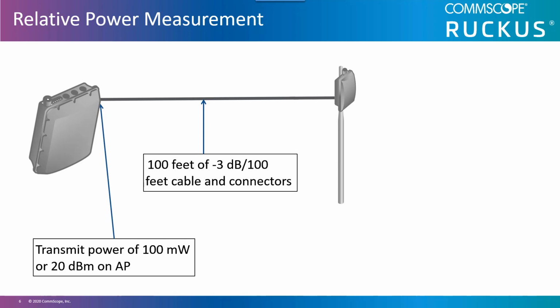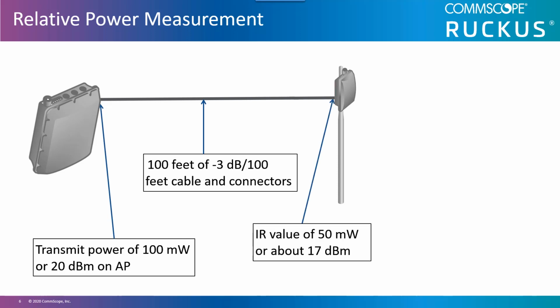Cables and connectors only introduce loss since they increase the amount of wired media the signal must traverse before striking the antenna. The media has some resistance in it, which introduces some loss into the transmission because there's resistance as the electric current goes through the medium. There's equipment that you can attach to the ends of cables to actually measure the true amount of intentionally radiated power the system is transferring to the antenna.